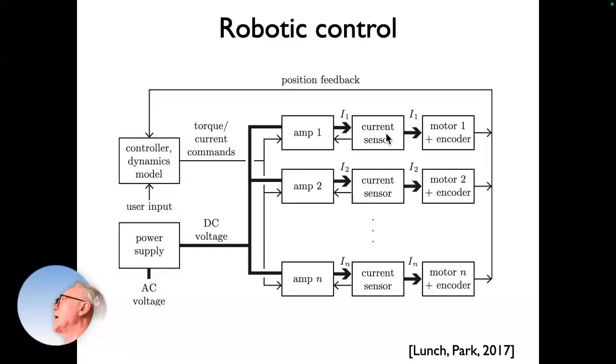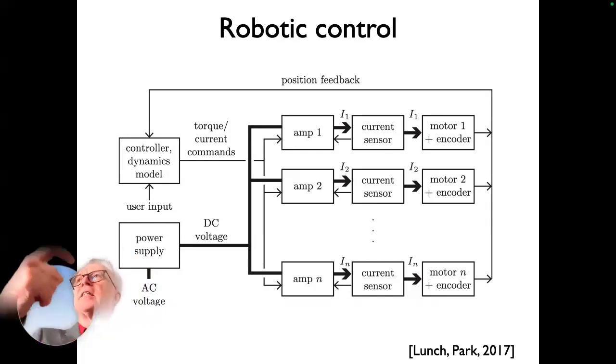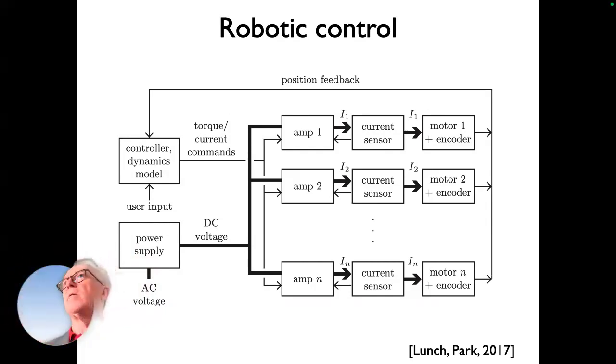By doing that well, you can make it so that the signal you send, even though it's an electrical signal, corresponds to a desired torque. It's not going to be exactly the same, but it's a very good approximation. So very often you can neglect the difference between the desired torque of the motor and the actual torque, and you can say what electrical current I have to set to get the torque right. That makes control of these arms much easier. So that's why electric motors are so attractive for robots, right?